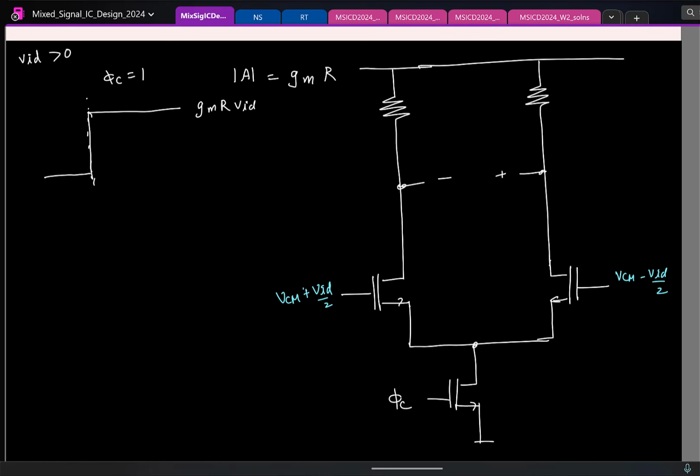Why? Remember, in life, you will have parasitic insects. Similarly, on chip, we have parasitic capacitors. So there will always be a parasitic capacitor from every node to ground. Which means the capacitor voltage cannot change instantly, because if it were to change instantly, impulsive currents need to be provided.